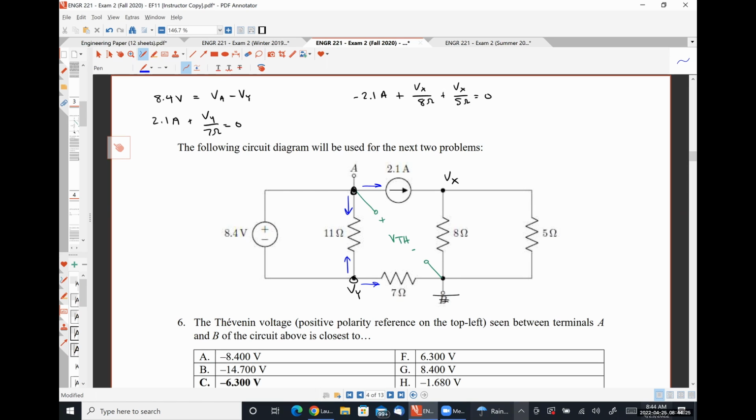So I would argue that it doesn't short out any particular elements. Now it might short out combinations of things, but that's kind of hard to see and quantify easily. So because the short circuit isn't directly in parallel with anything, I would definitely go with a full circuit analysis approach just to cover myself and make sure I didn't make a mistake.